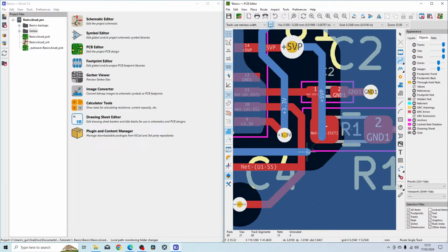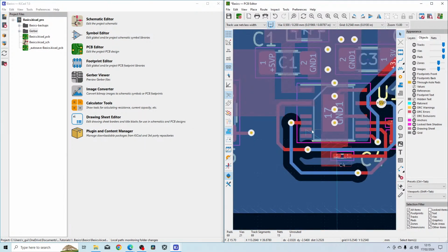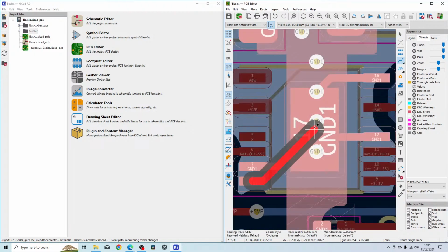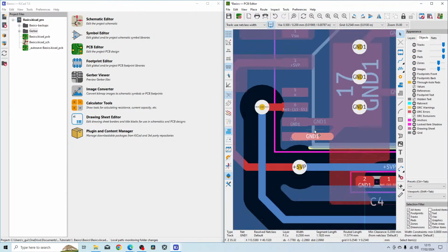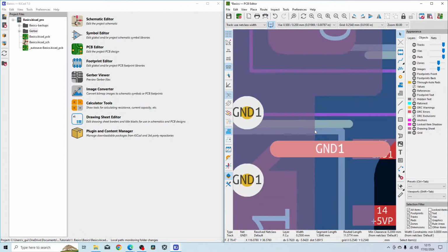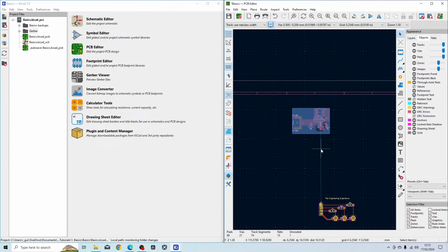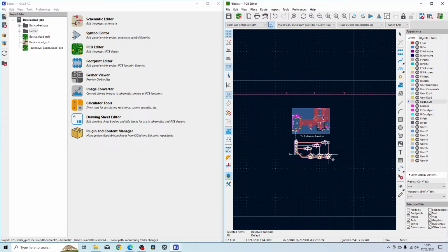That's connected, and finally you should see that we have everything connected except for these 2 points here, which can just go to the ground plane there. And what I'm going to do is make sure that, yep, they're the size of the track. I mean, that'll be fine. So the ground plane starts over here and they're connecting straight there, so that's not a problem at all. And quickly put down an edge layer on this board. Well, let me move this in here as well.